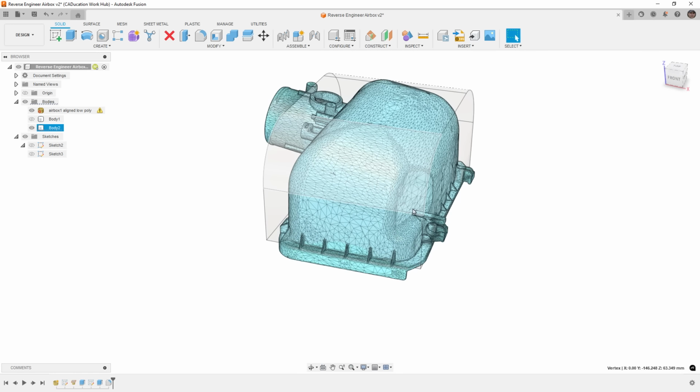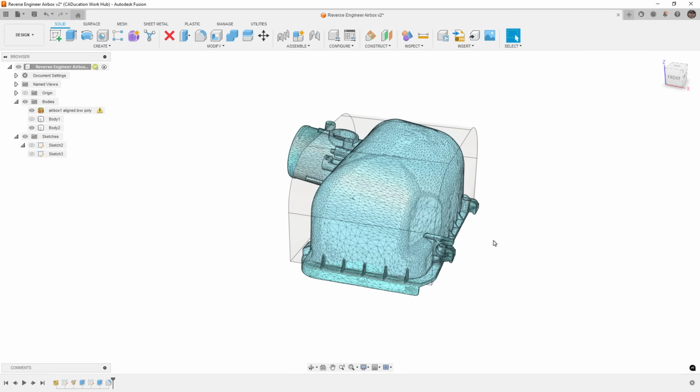So when I look at a shape like this, I have a couple of thoughts that come to mind. One is to split up this bottom section and everything above these fillets or arcs in and work with the bottom section and then build the top from there. The other thing that we can do is to try to cut away some geometry. That's a little bit harder to do. It's a little bit harder to visualize and figure out. So anytime you have a complex shape, breaking it into multiple parts can often be a pretty good way to work at it.